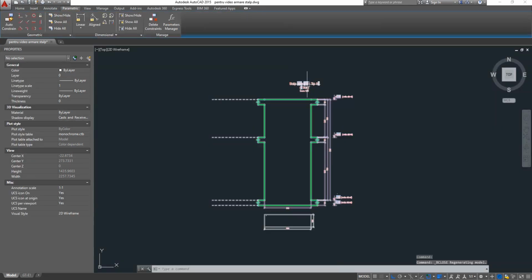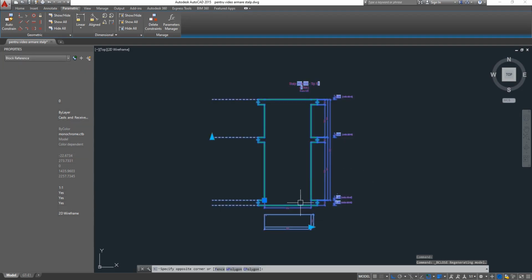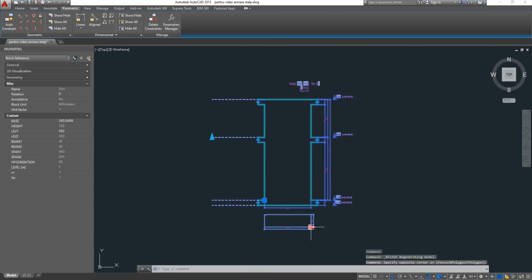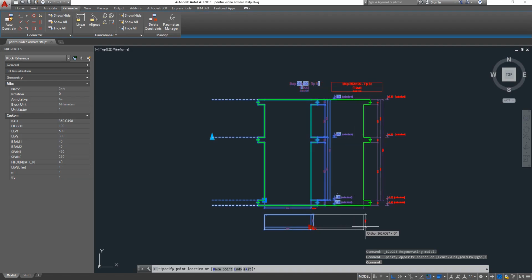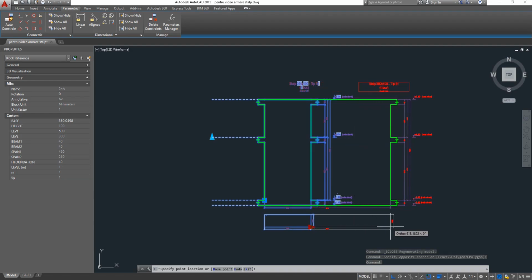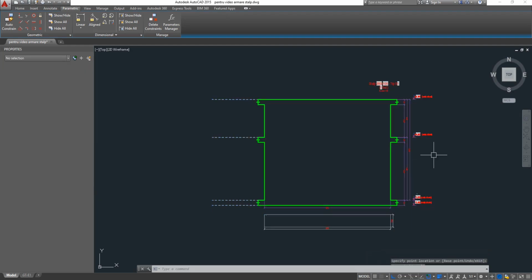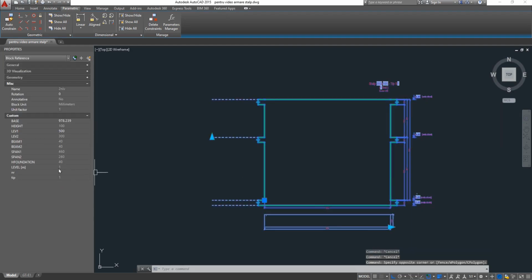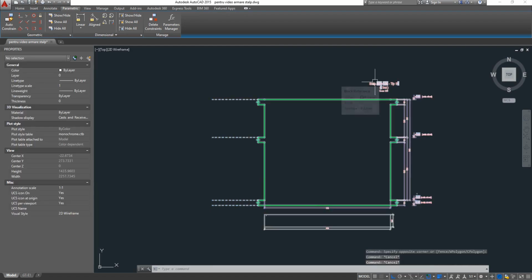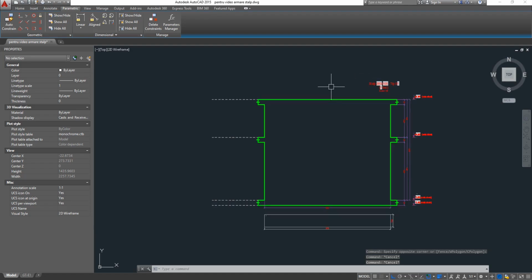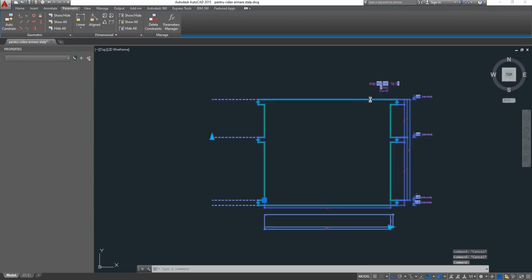and there you go. Now it's dragged on the right side, and as I'm dragging the width of the cross section of the column, the text follows at a distance multiplier of 1, okay? It follows the parameter. But as I said, I want to keep it at the middle. So how can I do that?